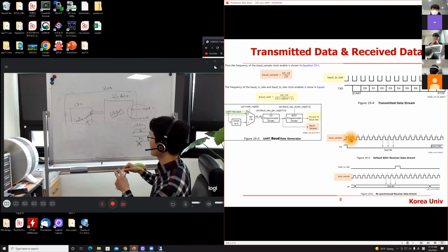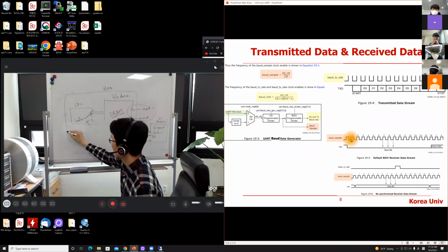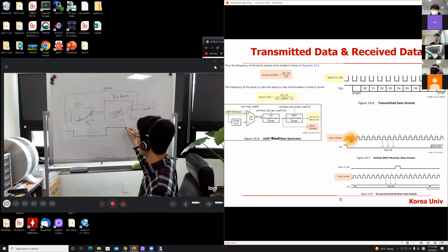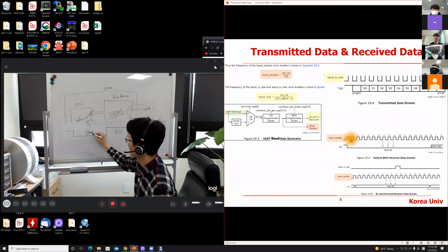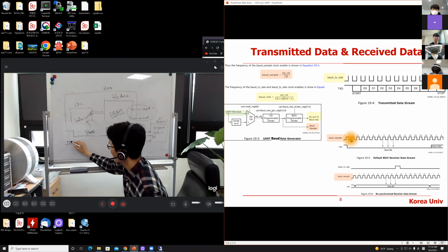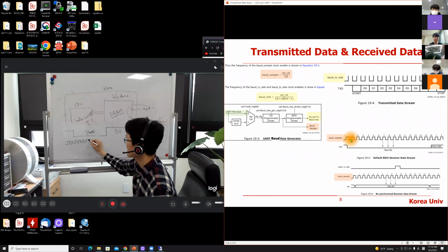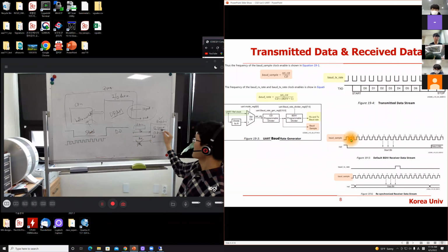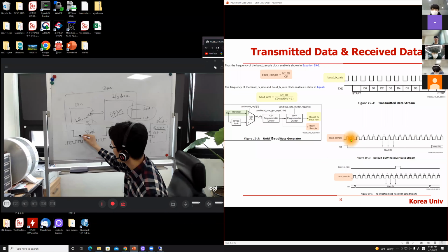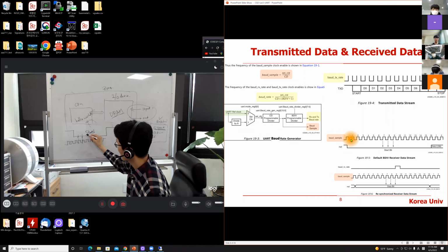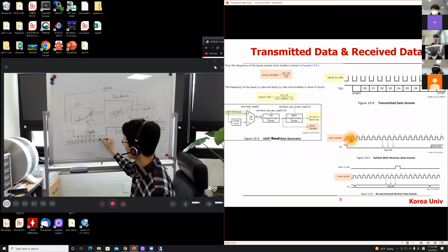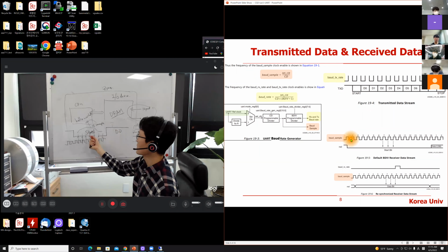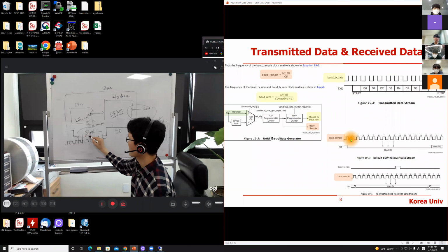I'm trying to explain a little bit of the internal mechanism of UART. Start bit and D0. Internally you have a clock, which is running 16 times faster than this data transfer speed. At every rising edge of the clock, UART is checking this bit. Then it is taking the midpoint of the 16 samples to figure out the data. So I know this is a start bit.